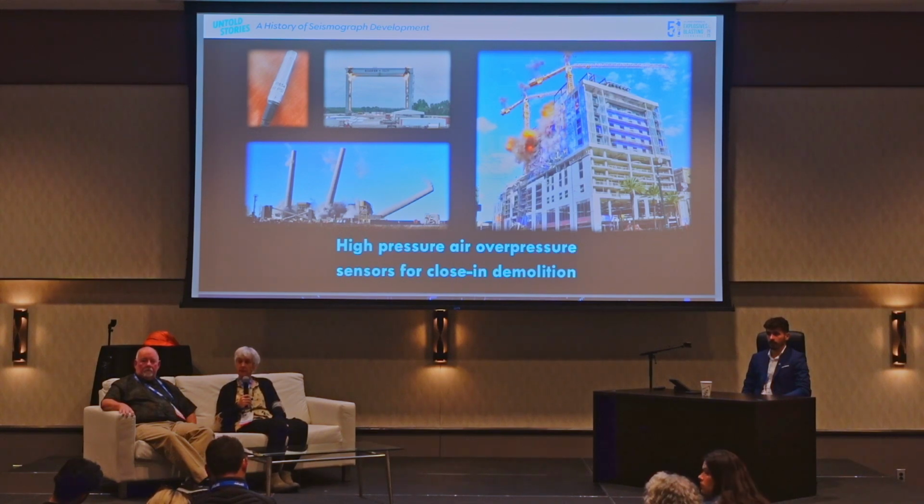But we had in the pre-blast inspection the evidence of the window already being cracked. But I was right beside that building when the window fell out and crashed. You can hear it in the video, so there's no doubt about that one. The other one was an on-site structure that was going to be torn down anyway, but I put a seismograph there because I knew there was a good chance that the windows may be broken.